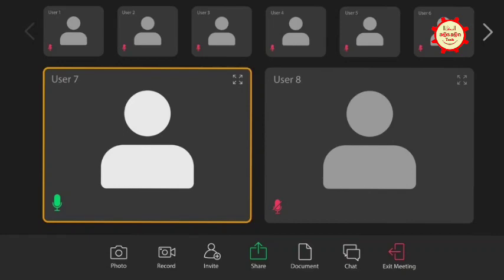If some nozzles or something come on that side, how will it be? You will change that flow. No, if there is any nozzle, tie rod is not allowed in the inlet side. The inlet will always be free. We shift the sliding strip. These are all taken care of before. We just put an offset of the nozzle ID, how much, and then we track where we have to establish the sliding strip.